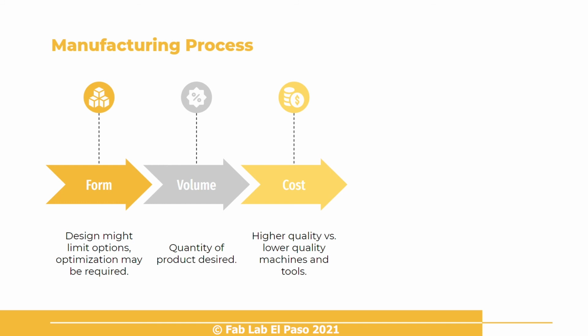For example, a lot of people are using 3D printed molds for short-run productions, and while the prints themselves are inexpensive, they only last for a couple hundred parts at most. On the other hand, you could spend a lot more money upfront to create a CNC machined master mold. The quality and durability will be higher, and you can make many more parts. Depending on the total volume or quantity of parts in a production run, the fabrication cost per part typically decreases with larger quantities.